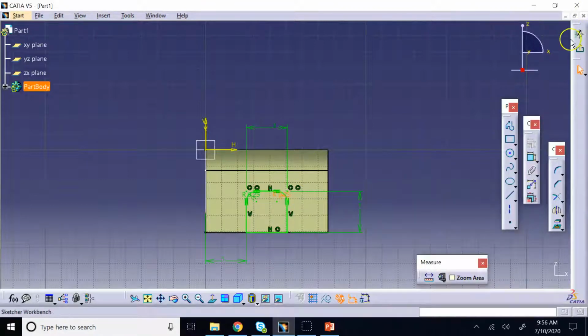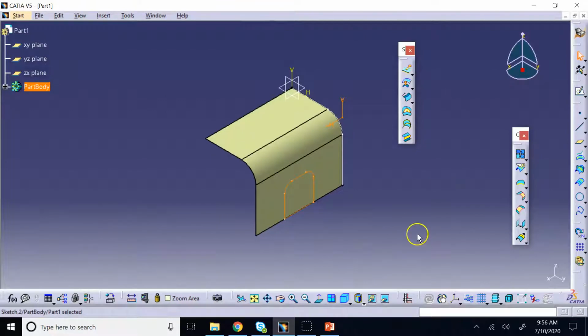There we go. And we get out. Now, in surfaces, we don't have a cut extrude command, okay? Because there is no solid thing, so we cannot really cut extrude. As you can see here, we have the command for offset, we have for sweep, we have for fill, we have for loft, blend, and so on and so forth, but there is no cut extrude command.